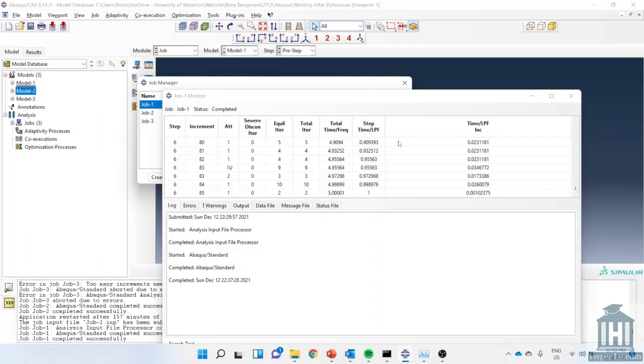As you can see, the first model is being completed. We had a few attempts, but they are during the process, which is okay. Already we can see, for example here, sometimes we reach the 3rd attempt. So if you see you have close to the 5th or 6th attempt, or you face too many attempts in the middle of the simulation, you also can go to the approach that we explained previously, changing the number of maximum attempts. Okay, this is the first part.